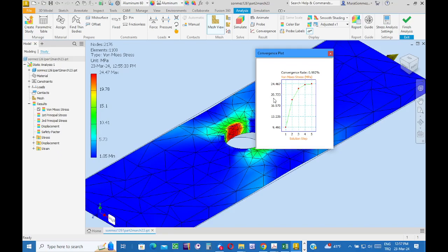This is the answer. Hocam, how many finite elements need to be used for finding the solution more accurately? If you use few finite elements, then you may find the result 16 megapascal. It is misleading. Increase the mesh number, increase the finite elements, and then repeat the calculation. Third repetition, you see not 9 megapascal, but say 24 megapascal. But after the fourth running, the difference between the result of the fourth running and the next running is negligible, because you see the curve converging.